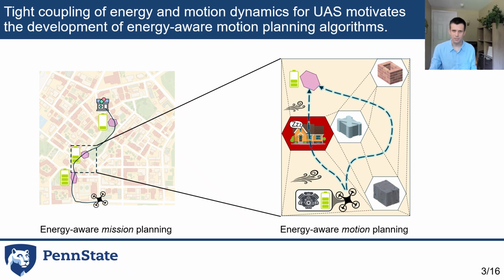So in general, this is a non-convex problem as the drone may have to navigate around obstacles in the environment. And this may be further complicated by the presence of quiet areas, which in this graphic are depicted as the red region. And these may, for instance, carry some constraints on engine power usage.